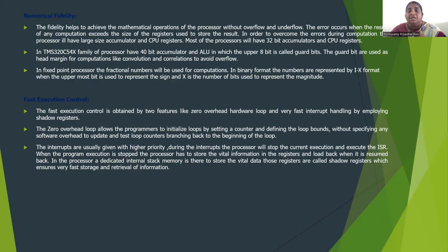It has a 32-bit accumulator and CPU register. Especially the 54 series has a 40-bit accumulator, with the upper 8 bits called guard bits. The guard bits are used as headroom for operations like convolutions and correlations to avoid overflow.